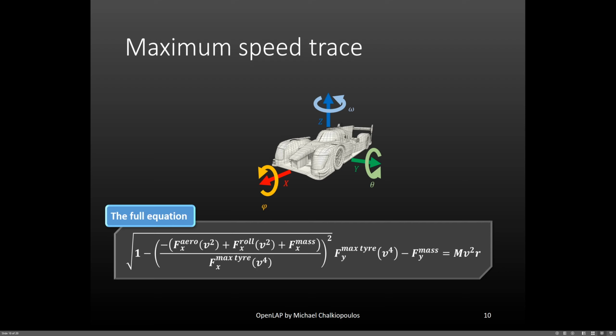So this is why I use the method I just described to find the pure lateral condition and don't solve an equation directly. The idea is that I omit the ellipse factor, which is basically the square root in the beginning, making this a solvable polynomial that I use to get the first estimation of the final solution. In my experience, this makes the correction loop run between 3 to 5 times before an acceptable value is found. I am aware of the fact that this method might underpredict the value by a very small amount.